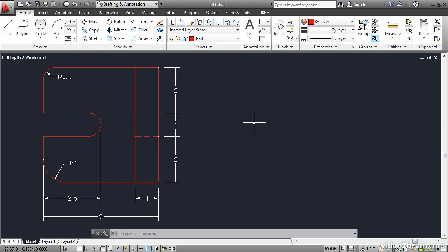In this lesson, we will explore grid and snap. The closest analogy to grid in the real world is graph paper. Snap, on the other hand, essentially quantizes space so that your cursor no longer moves continuously, but instead snaps from one place to another according to a spacing value that you set.